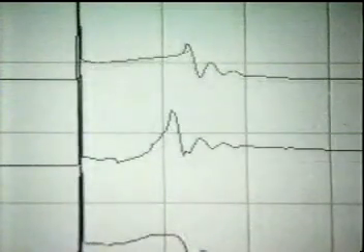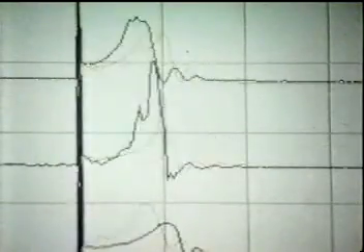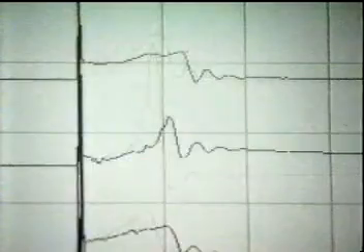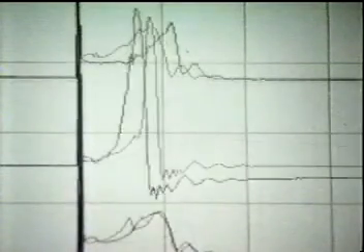One of the problems with these Multec injectors is that they do intermittently stick shut. This is a classic example of a car that needs injector cleaning. But at any rate, to show you that number 3 cylinder spark line under dynamic loaded conditions, let's go ahead and put the car in drive and power brake it and watch what happens in cylinder number 3 spark line. Now you can see cylinder number 3 spark line is bending abruptly upward with a very, very high blowout point indicating a lean cylinder.